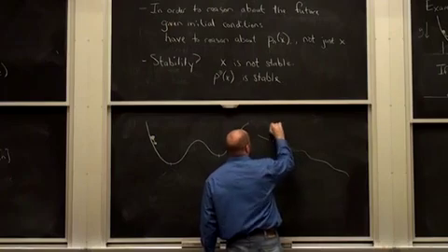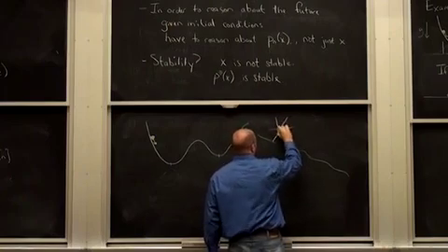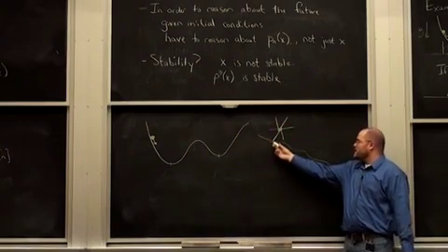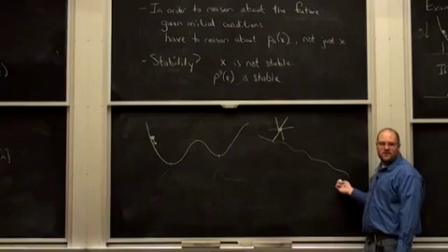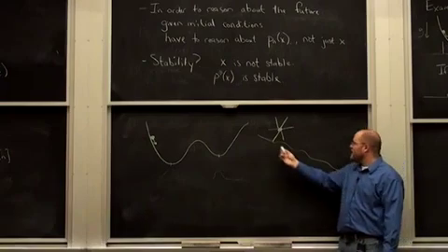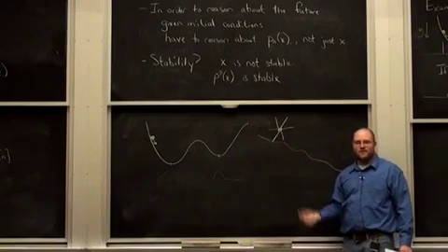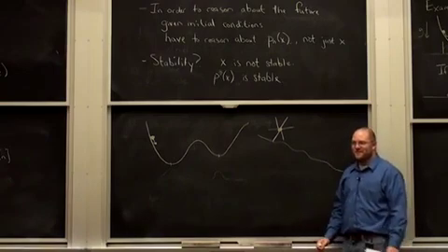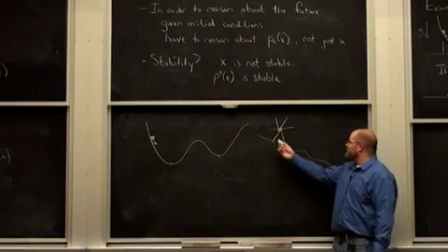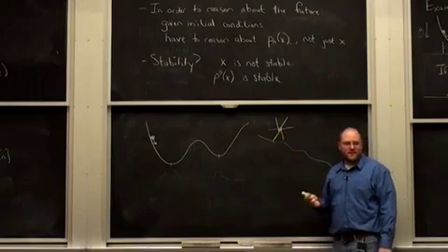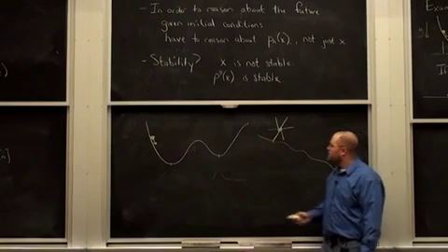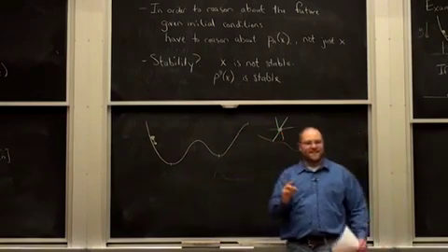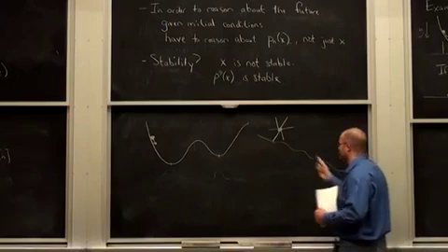Take your rimless wheel dynamics, and let's say instead of walking down some constant ramp, on every step the ramp angle is drawn from some distribution. So this is passive walking on rough terrain. And it turns out it's not following a limit cycle anymore. But its long-term probability distribution is, well, there's a slightly more complicated story.